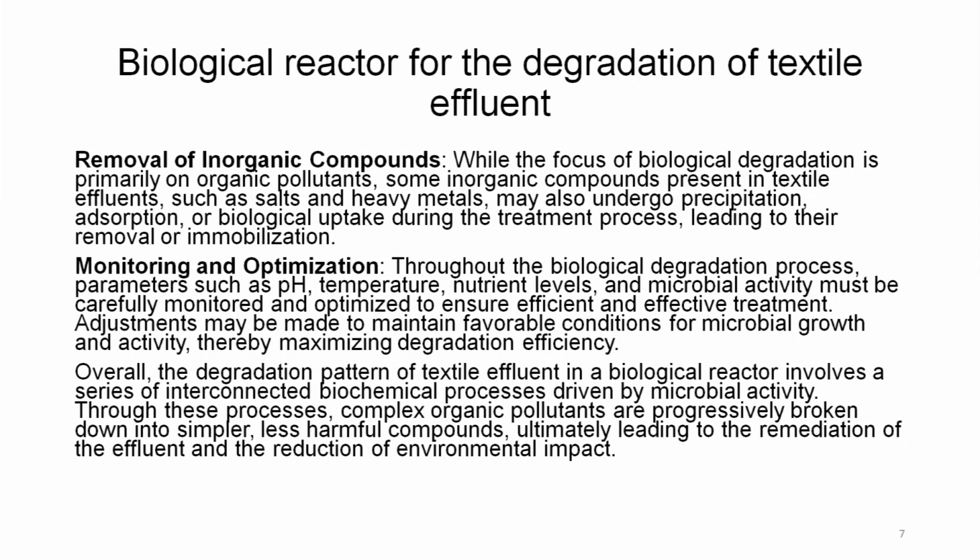Monitoring and optimization. Throughout the biological degradation process, parameters such as pH, temperature, nutrient level and microbial activity must be carefully monitored and optimized to ensure efficient and effective treatment. Adjustments may be made to maintain favorable conditions for microbial growth and activity, thereby maximizing degradation efficiency.